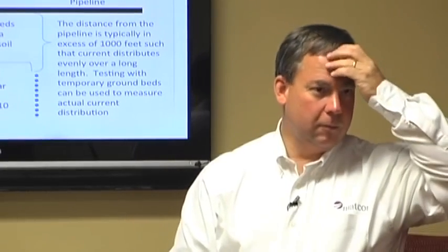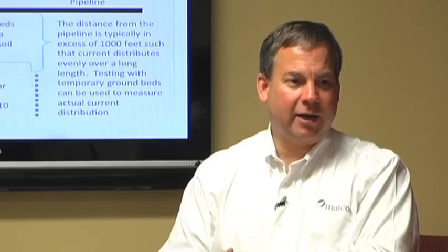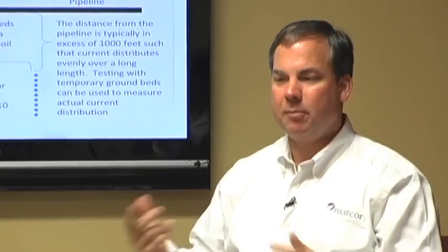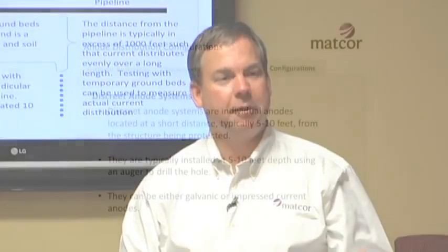Is that our linear anode? That's where our MMPs are used, our packaged canister anodes. MMPs are used for, correct, that they're commonly used, tubular anodes. Linear anode can also be used for a remote horizontal ground bed.